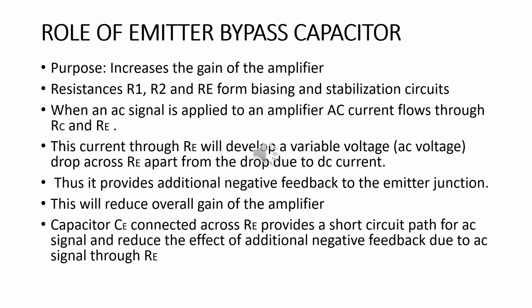That will provide a short circuit path for the AC signal and reduce the effect of additional negative feedback due to the AC signal through RE. Thus, it increases the gain of the amplifier.